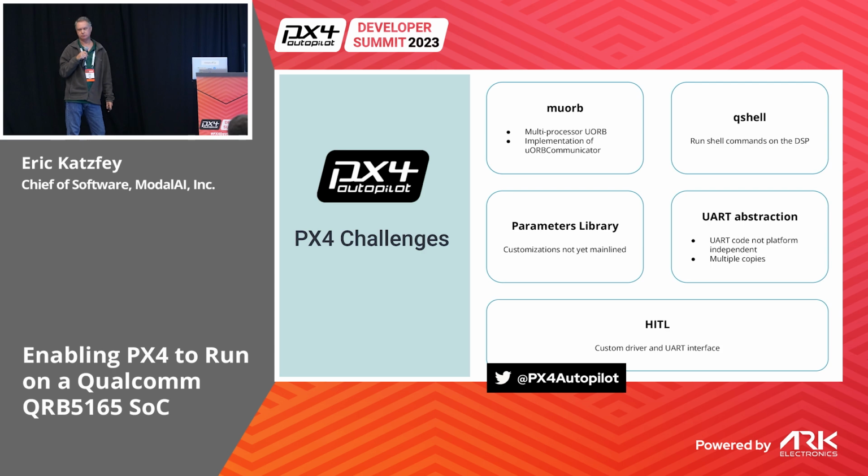But now we've got this split architecture. How do you get UORB topics that are flowing around on the applications processor and UORB topics that are going around on the DSP? How do they get back and forth? That's this module called MUORB. That stands for multiprocessor UORB.